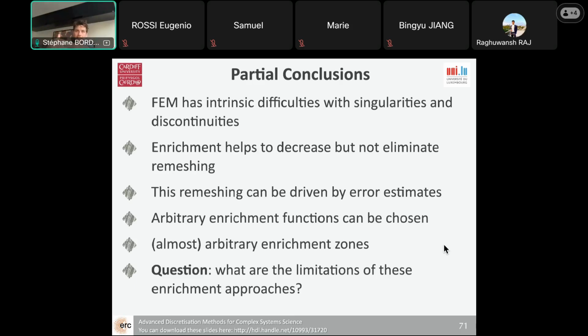The Griffith crack energy is equal to 2 times the surface energy of each atomic layer multiplied by the area of the crack, 2 gamma A. So this 2 gamma A is the energy that the crack needs to exist. Then you compute the energy that it needs to grow, which is related to how much it grows and the intensity of the stresses in that region.